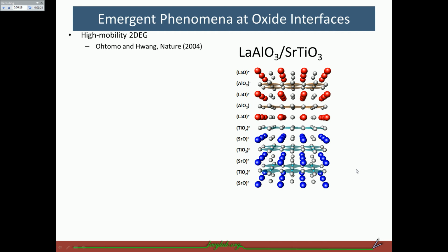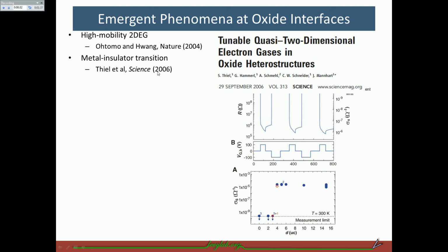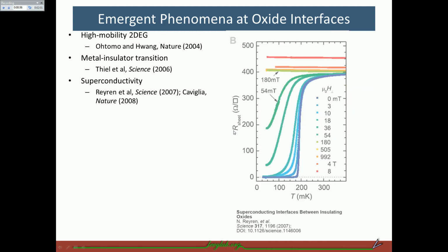In this oxide interface, the electron interactions are intense, leading to novel phenomena like the 2D electron gas, which can be tuned by the back gate voltage through the metal-insulator transition region, and also by the thickness of the LAO. There exists a critical thickness of 3 unit cells: above that the interface is conducting, and at 3 unit cells or below the interface is insulating.